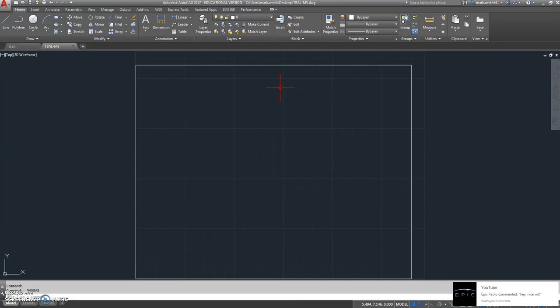So let's focus on this top corner of the drawing right here, and let's create what is called the rev box. If we look at the rev box, we can see it's 5 inches long, it's 1 1/8 tall, and the lines are all 0.375 down from each other, and they're 0.75 wide in the first one, and the second one is 1.75. I can't use snap for this one because we're not setting a number divisible by 0.375, so even though I set it up, it won't really work very well.